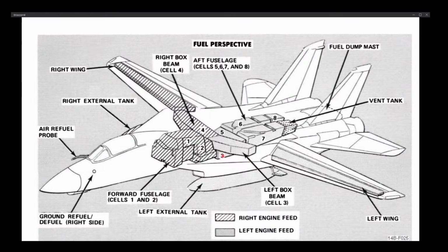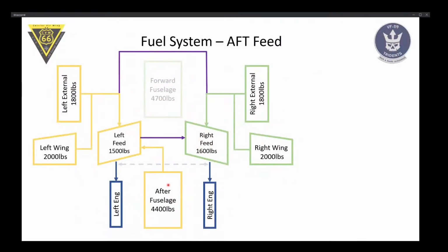And if you wonder how this transfer works between the tanks, because there's no fuel controls for any kind of fuel pump, this is done using motive flow. So basically there's pipes running around all the tanks, and they use the Venturi effect to basically draw. So basically you pump fuel from this tank into this tank to get more fuel back.